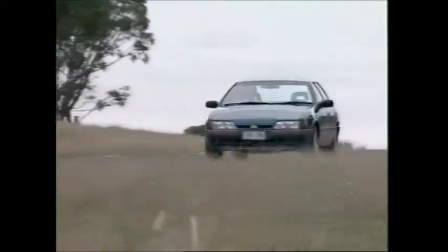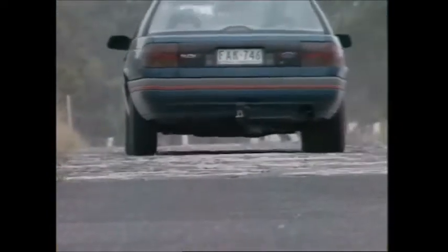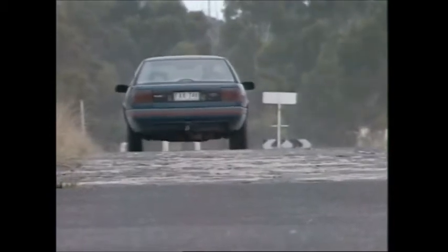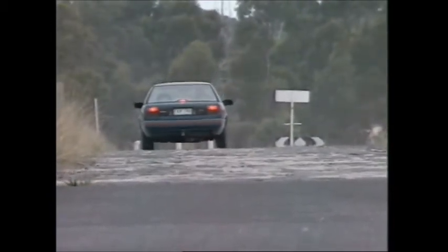The stiff bracing layer links the cord loops together to give fore and aft stability when accelerating or braking, and it prevents any movement of the cords during cornering. The cord plies flex and deform only in the area above the road contact patch. There are no heavy plies to distort, and flexing of the thin casing generates little heat, which is easily dispersed. A radial ply tyre runs cooler than a comparable cross-ply tyre, and this increases tread life. Also, a radial tyre has less rolling resistance as it moves over the road surface.